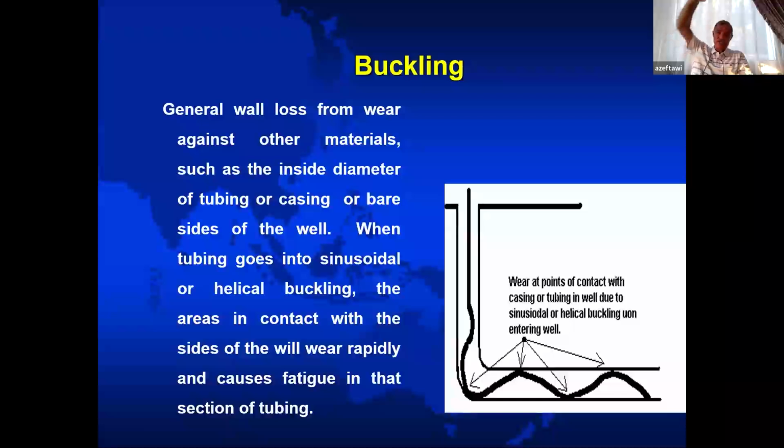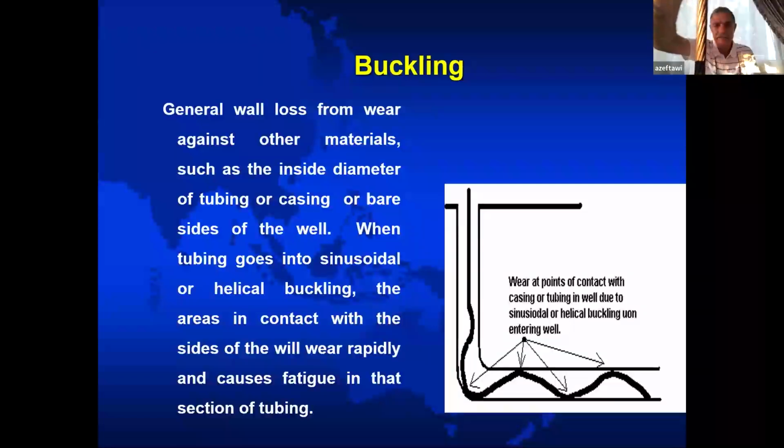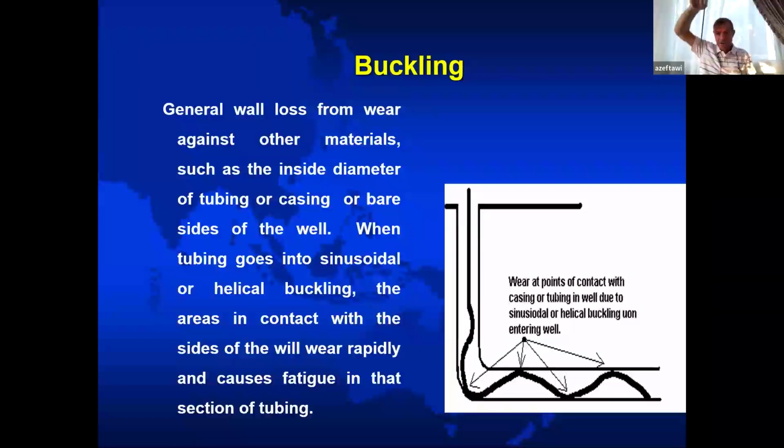The coil tubing doesn't go straight down. The wireline does. Yani, if you have an E-line like this one, an E-line or braided line, this is a braided line. Here it is. This, it goes straight, yes. But the coil tubing doesn't. The coil tubing goes in helical like that. So you are giving free area for the pipe to move freely. So buckling might happen even in the vertical section as well.